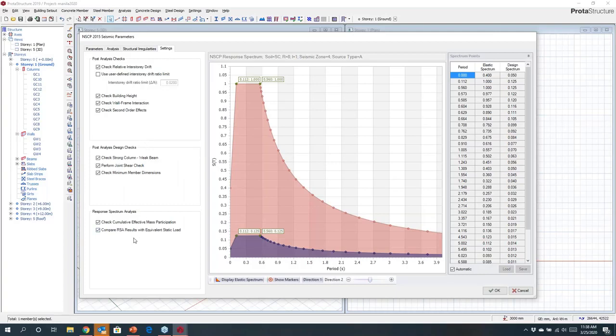We will also automatically scale base shear. So typically you'll calculate your equivalent static base shear. And if you are normally running an RSA analysis, at the end of this, you'll need to scale the results up. Okay, but depending on the number of modes that you run, it won't normally capture the full base shear, and you'll need to make an adjustment. We automatically do this for you. So we will calculate that, and we will apply that. If you don't want to apply it, of course, you can turn this off.